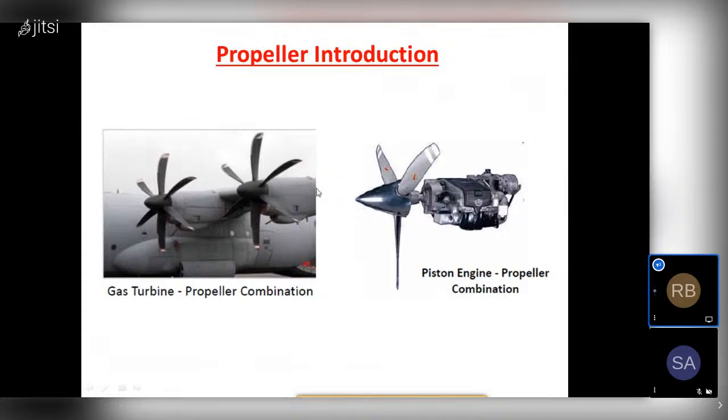Here we have it in a manner analogous to rotating a screw through a solid. So the blades of a propeller act as a rotating wing, and these blades produce a force through the application of Newton's third law, generating a difference in pressure between the forward and rearward surface of these aerofoil blades.